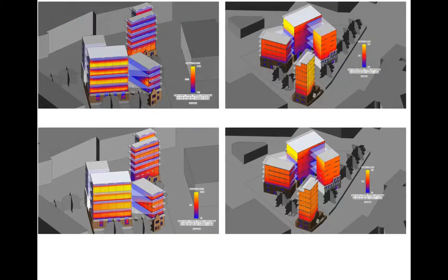Okay, solar radiation, as I mentioned before. In this example, this is a very detailed analysis of the energy from the sun impacting on this building. And we've got some different comparisons here. If you look on the bottom, we have the building with a slightly different shading configuration. And if you look at the top view, there's a deeper shading system, and you can see the impact of that here in terms of the reduction of energy on that facade below the shading.